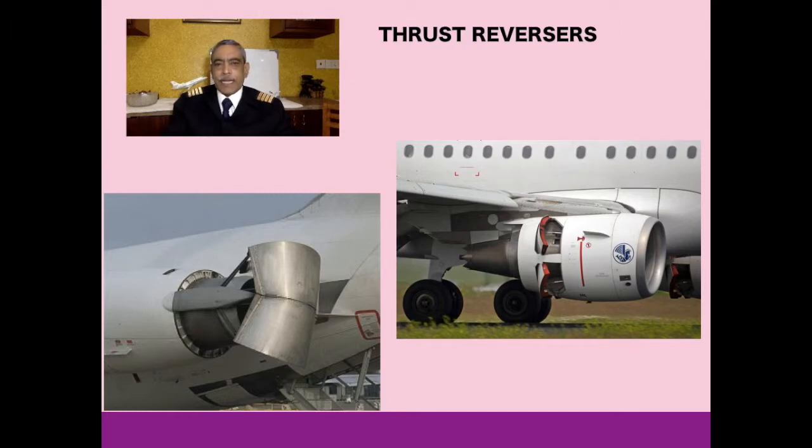You must appreciate that the aircraft lands at very high speeds and the brake system may not be good enough to commence braking at such high speeds because it may generate very high levels of temperature. Therefore, almost all jet engines have thrust reverser systems which produce reverse direction thrust to decelerate the aircraft immediately after landing. There are two types of reverse thrusts that are employed in aircraft.